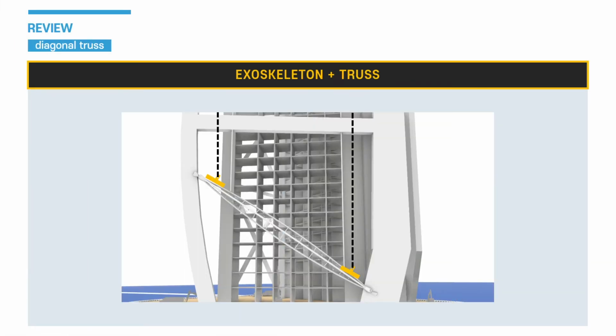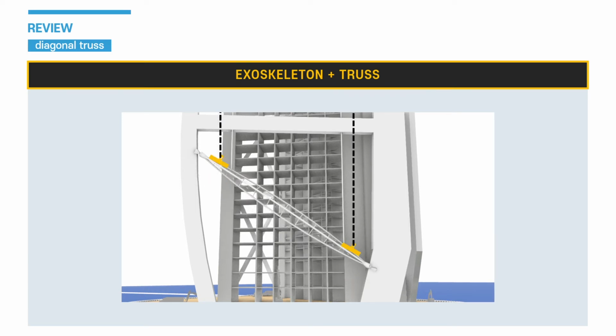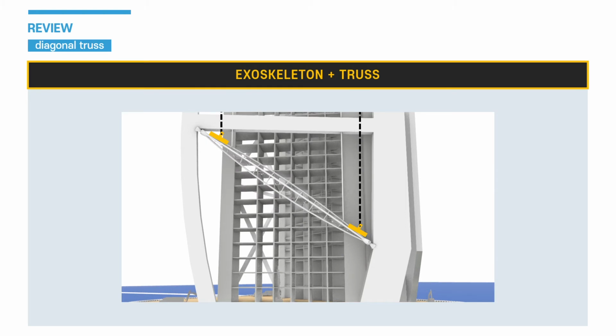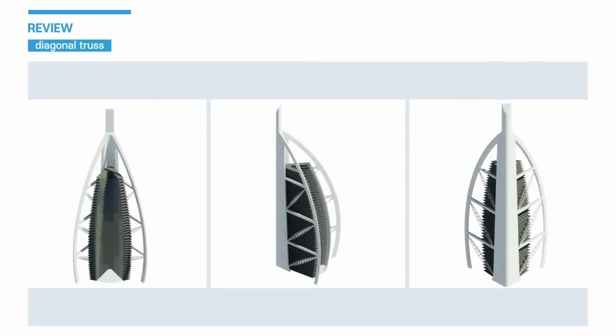Then, a cable holding 225 tons was attached to both ends of the truss, and 2 giant wheels raised the spiral truss to the connecting position. At this time, the truss was raised to the angle calculated in advance, so that it could be properly fastened to the pin. This is an image modeled using Revit of the concrete core, exoskeleton, and spiral truss of Burj Arab.